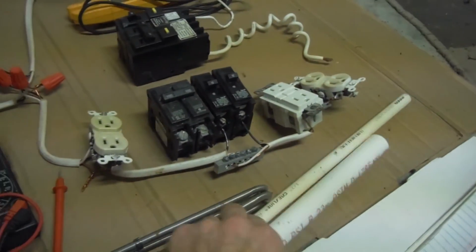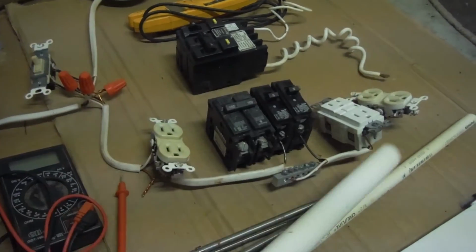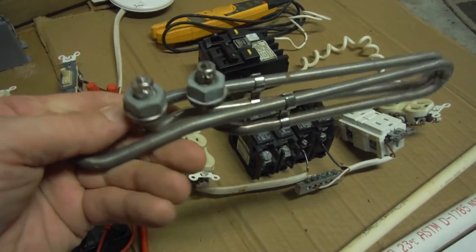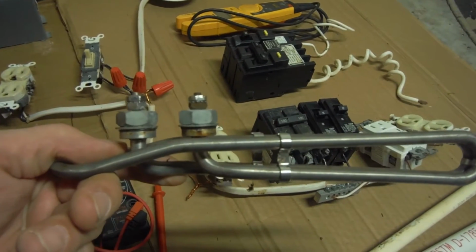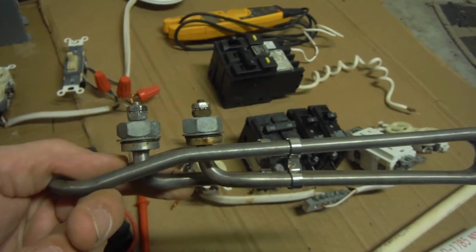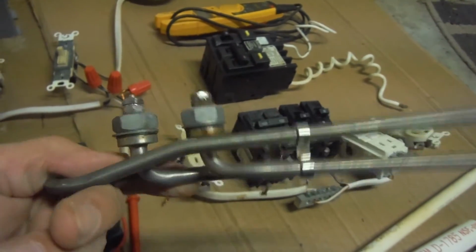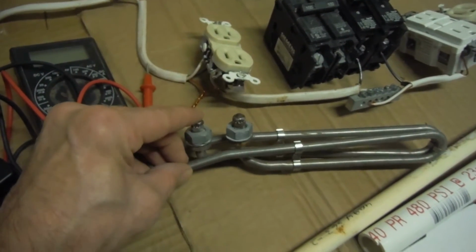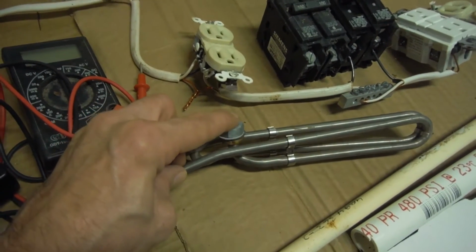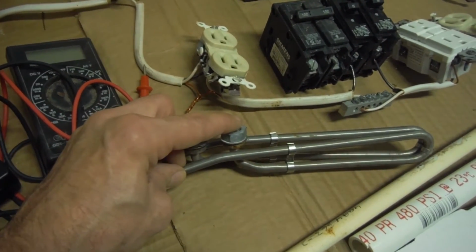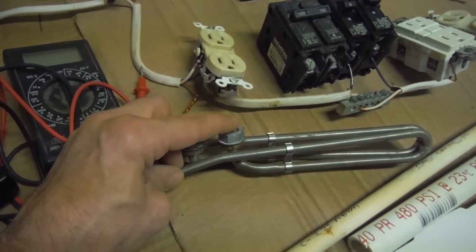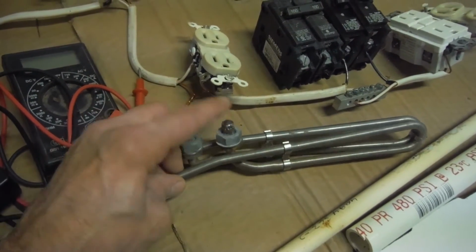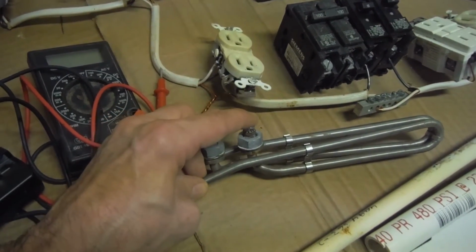Another thing, with the resistance in the pipe, another thing that's used in resistance here is a heating element. This is from a hot tub, but this is the same thing for, say, your water heater, your stove, your oven, all that different stuff if it's electric. Pretty much what it is, you've got your two hots coming in. You got 120 coming in over here, 120 coming in over here. Stove, oven. Nah, I think some of the stoves are 120, but ovens are usually 240. The water heaters usually 240. Hot tubs are usually 240. You got 120 coming in, 120 coming in.